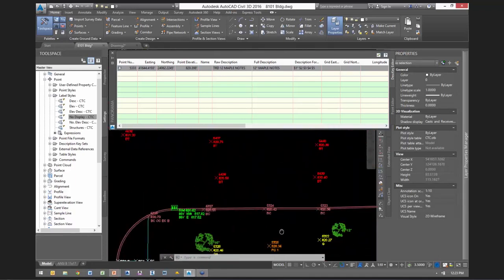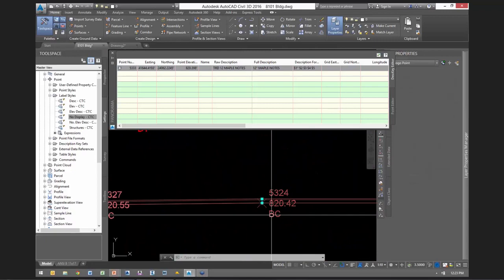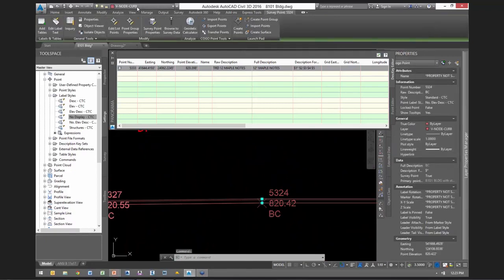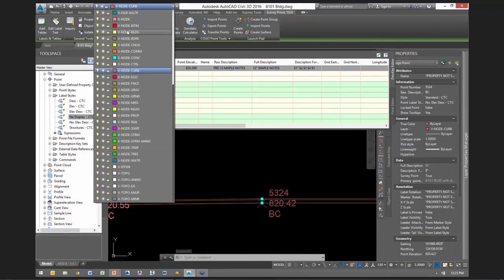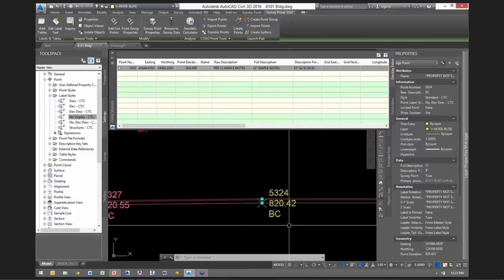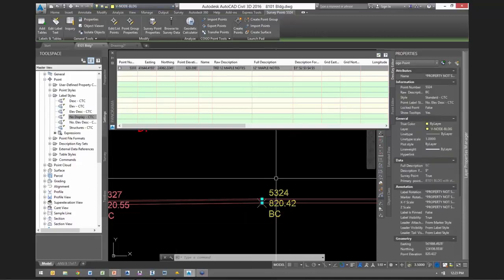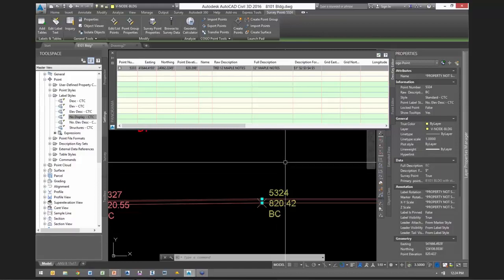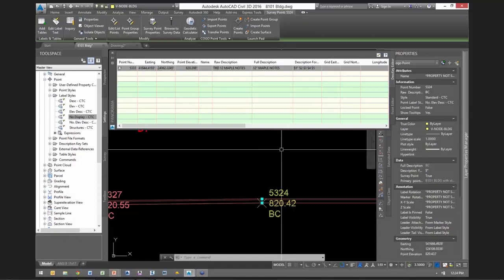So putting layer 0 in it allows a point. Let's just grab this back, a curve point. If there's layer 0 and all those styles that are associated with it, if I just simply change the layer, the color will change with it. This really supports conventional kind of AutoCAD behavior. And for perhaps project managers or light Civil 3D users who don't fully understand all the styles and everything, this can be really helpful.